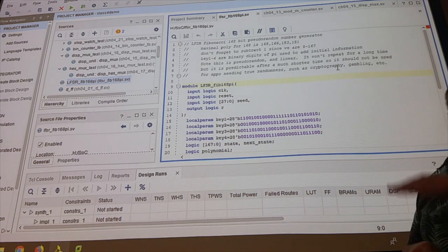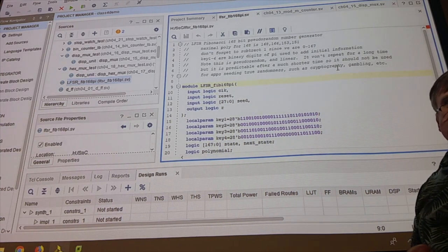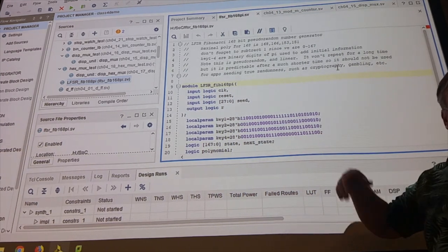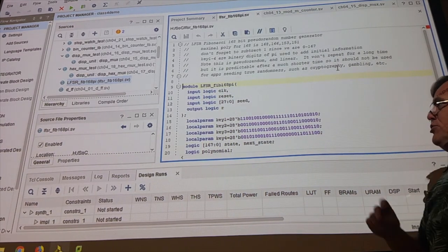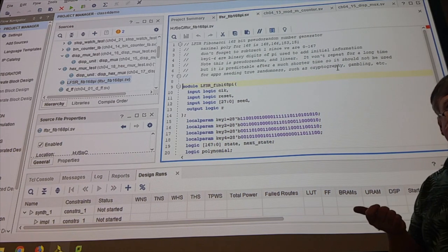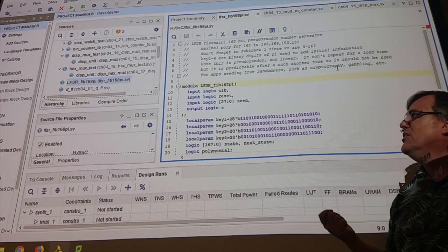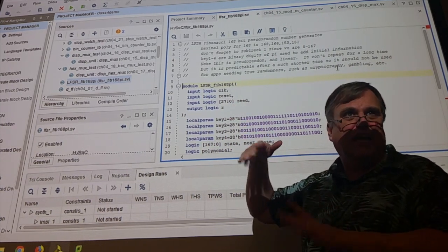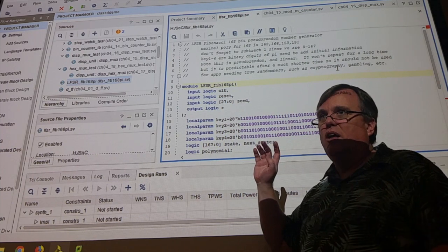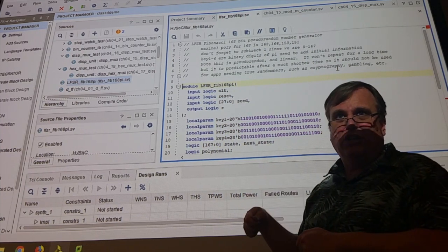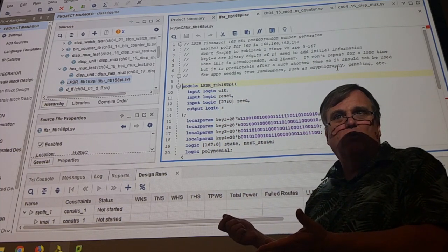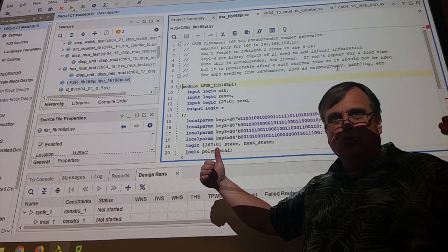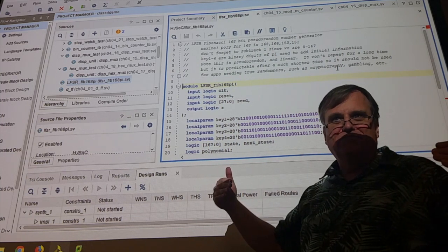Now, in our case, it's utterly irrelevant, because by the time you start this and the time you read it, it will have gone through so much it won't matter. I do suggest you do the seed and the not seed, because of this. Since I'm only using 28 bits for the seed, because that's what's needed to make the 168 nice and neat, you can use switches to generate that. But what if somebody left all the switches 0? Then you'd have all 0 in your register, which will always generate 0.